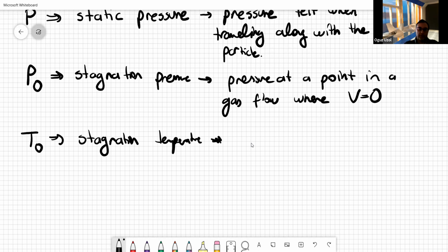It's the value of the temperature of the fluid element if you bring it to rest, meaning that if you take a fluid element, so let's have our fluid element here, it is at a certain temperature, so it does have a certain internal energy level, and it is moving, let's say. And since it's moving, it does also have a kinetic energy level, okay?